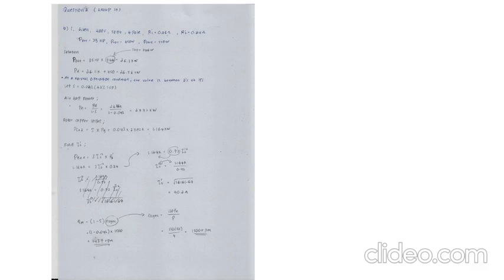And next we calculate the air gap power with the equation P_airgap equals P_D divided by 1 minus S. The P_D is from the P out plus P rotational. So 26.56 kilowatt divided by 1 minus 0.042, where we get the answer 27.72 kilowatt.